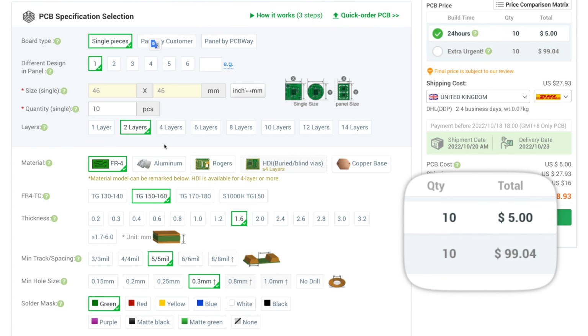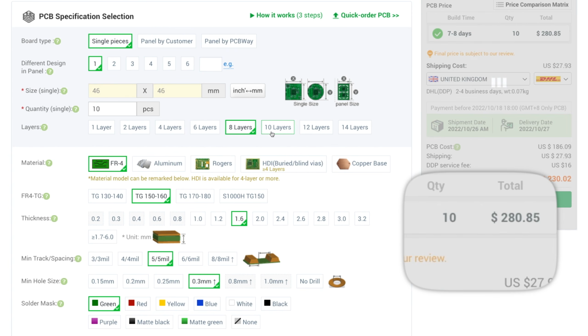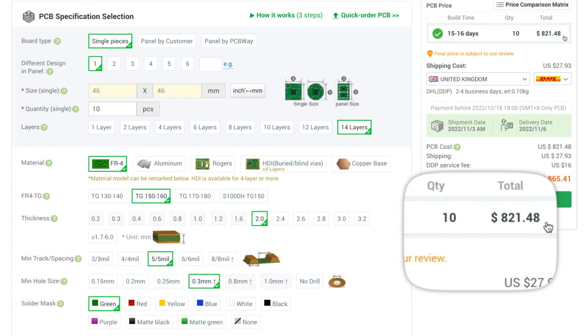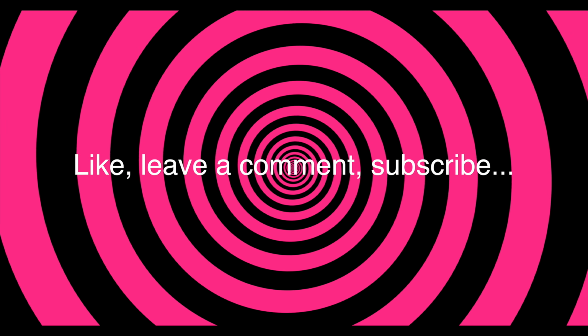Staying on the theme of keeping it cheap, we'll also be using a 2-layer board. Going up to a 4-layer board would increase the cost considerably. It is possible that these constraints will make our coils too weak to do anything, but we'll see once we have the PCBs manufactured. So how do we make a coil?